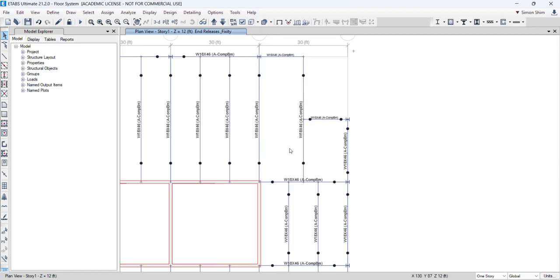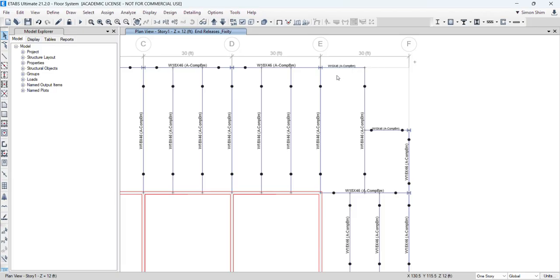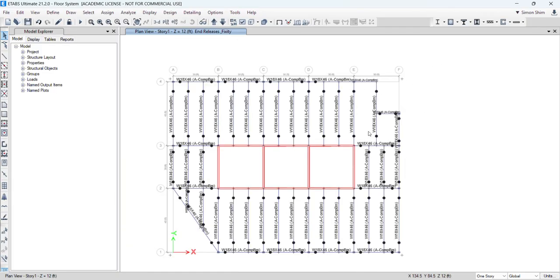In this case, all gravity loading is coming into this bay, beam to girder and beam to beam. But here this beam dumps the loading at each end, while at the top the beam reaction should be taken by this girder cantilever, right? So sometimes if you have this condition, this is a little bit of a next step, but you need to learn a little more strategy on how to deal with this.